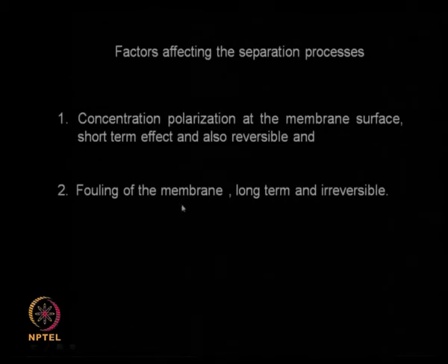Now this is a long term process, this is irreversible. Concentration polarization, I see at least, is reversible. I can stop the process and do some cleaning, and then again I start my membrane process, Cs will be equal to Cb. So it is a reversible process, a very short term effect, whereas fouling is a long term effect and it is irreversible.